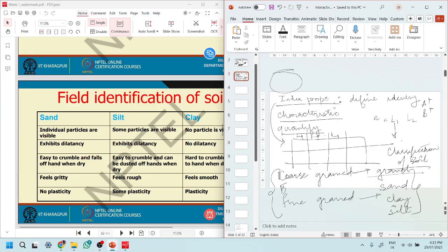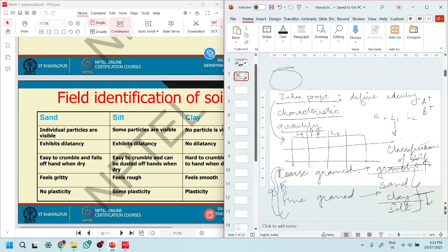If you put water on a gravelly path, it will just flow through because it has very high hydraulic conductivity, high permeability for water. But if you do the same with clay, it's going to stay on the surface for a longer time because the permeability is very low. And strength characteristics, permeability characteristics, compressibility characteristics, they vary very much between these.